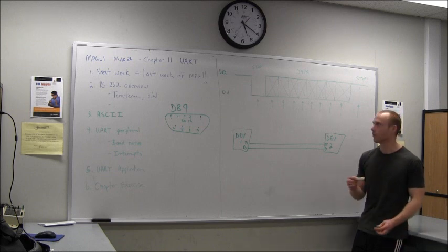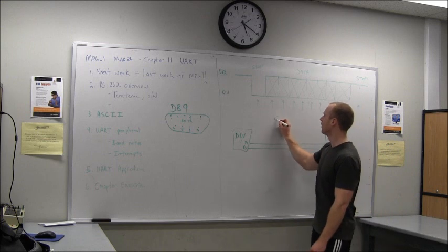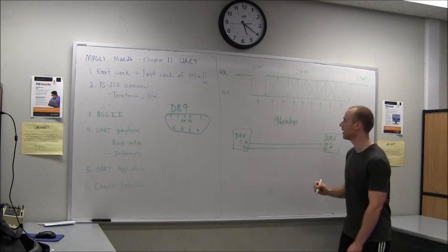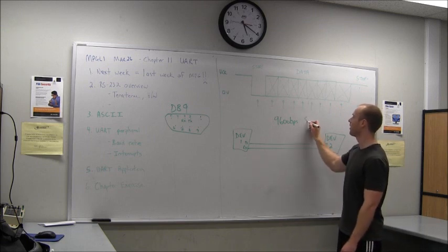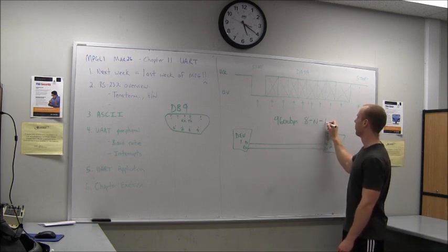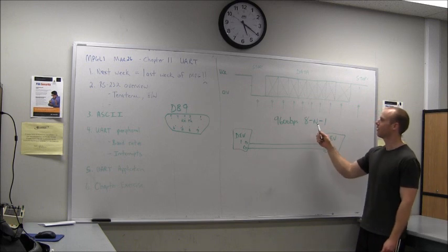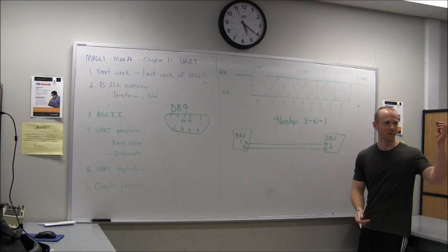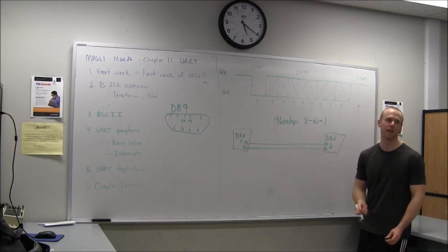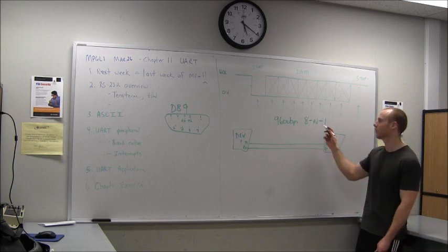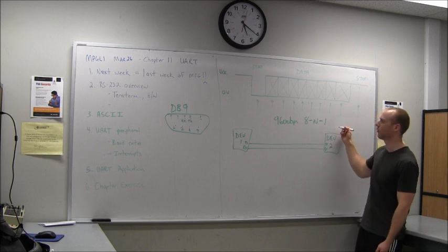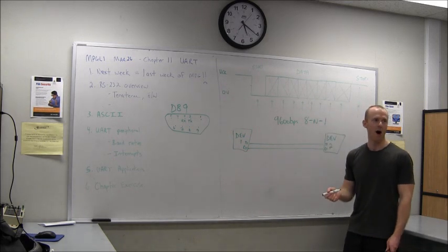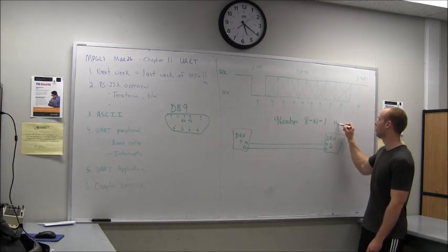So the very common setup that you'll see is 9600 BPS, which is your baud rate, and then 8, none, 1. So 8 data bits, no parity, 1 stop bit. You'll say that all the time. What's your protocol? Oh, I'm 96, 8, and 1. And you'll see that in text. So that's what that means. And then there's also flow control, which uses some of those additional lines, and that's usually off. So no flow.